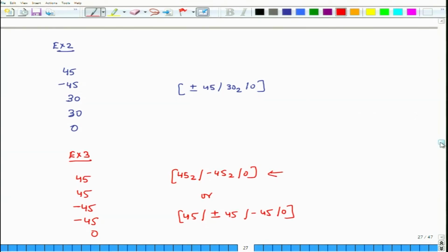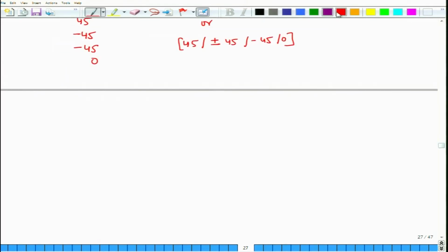Now, in this case the positive layer came first and then we had a negative layer. If it is just the other way around, then we do not use this sign, rather we use the minus plus sign. So, we will just do a quick example. This is just a question of conventions and it is not difficult stuff at all. So, 45, 0, minus 60, 60, 30, suppose these are the layers. So, this is example 4. Okay. So, this will be 45, 0, minus plus 60, 30.